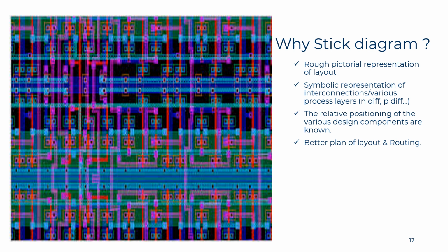If it is not done, it can result in deterioration of any one of the parameters which I told you: area, power or delay. One of these three will be affected. So if you want a proper, efficient layout and efficient routing, then going through the stick diagram is one of the ways in which you can benefit for obtaining an efficient layout.